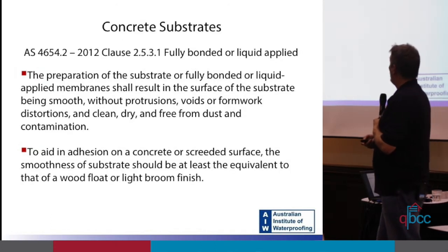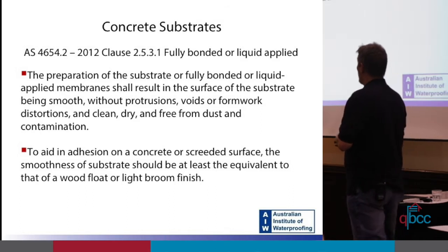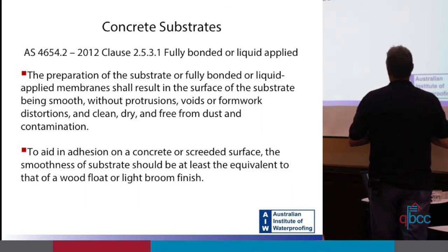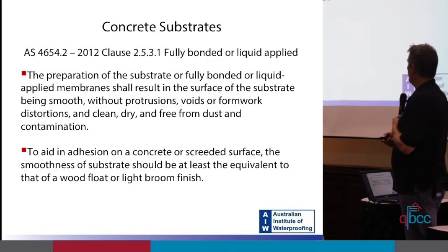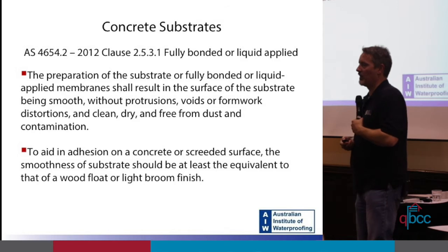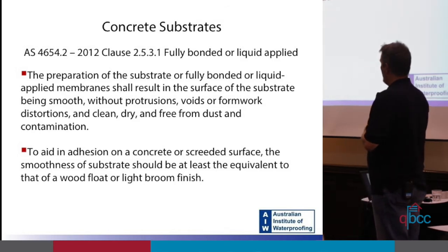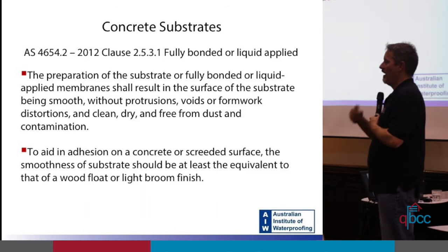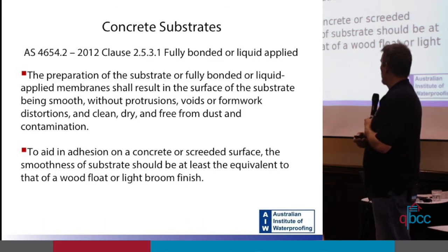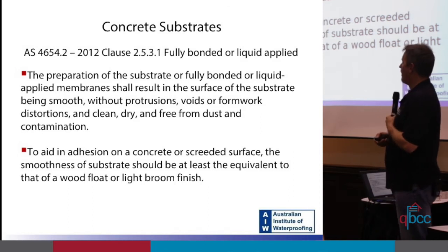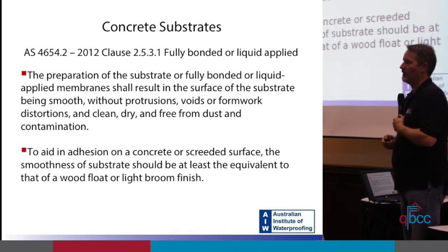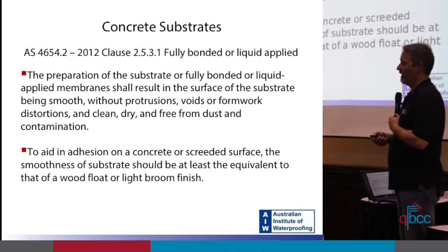A little bit more about concrete substrates. So the waterproofing standard says the preparation of the substrate for fully bonded or liquid applied membranes shall result in the surface of the substrate being smooth without protrusions, voids or formwork distortions, clean, dry and free from dust and contamination. Right, you'll find pretty much exactly that clause repeated in every manufacturer's data sheet. To aid in adhesion on a concrete or screeded surface, the smoothness of the substrate should be at least equivalent to that of a wood float or light broom finish. And I mean light broom finish.